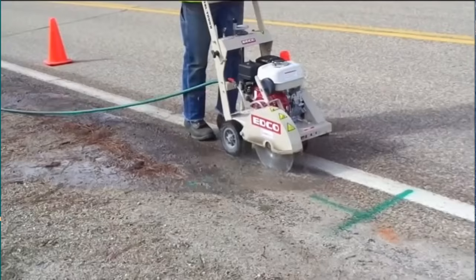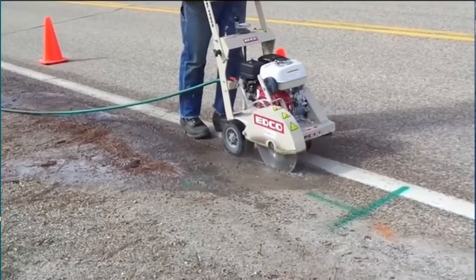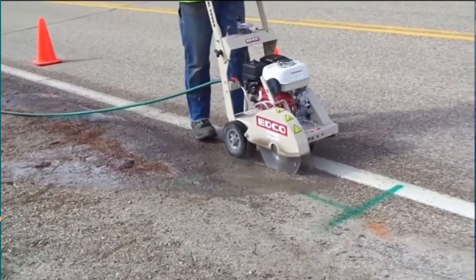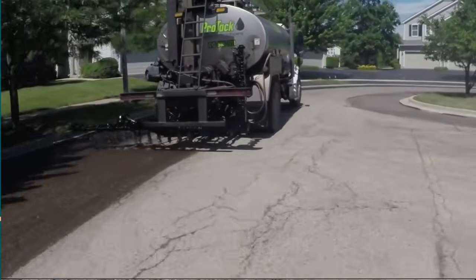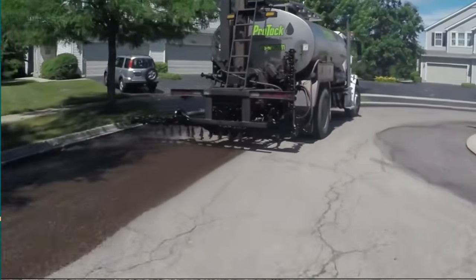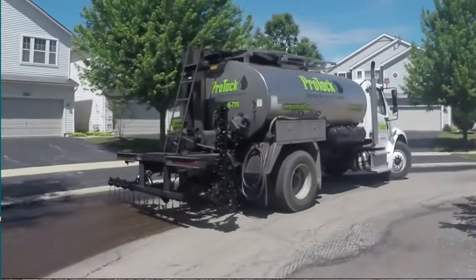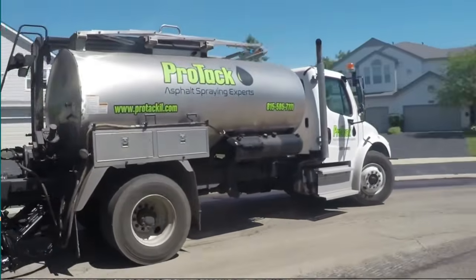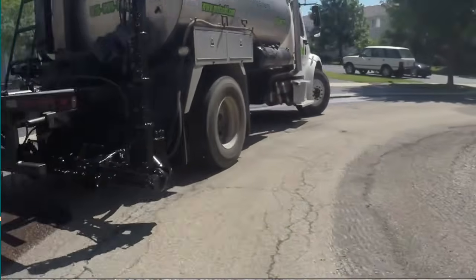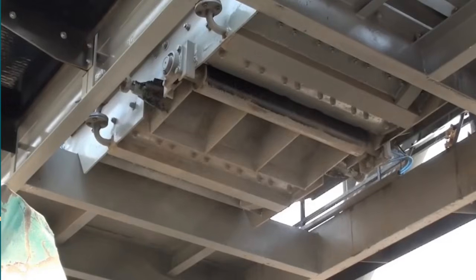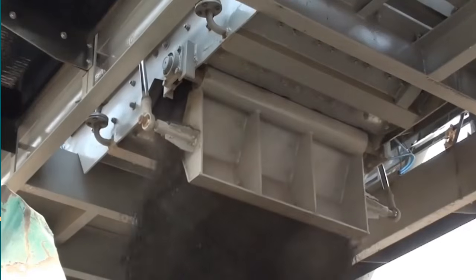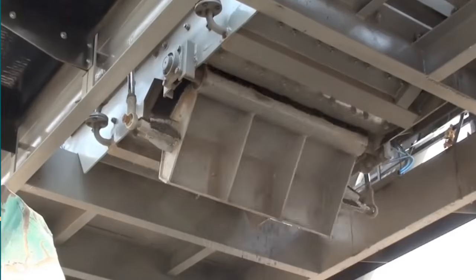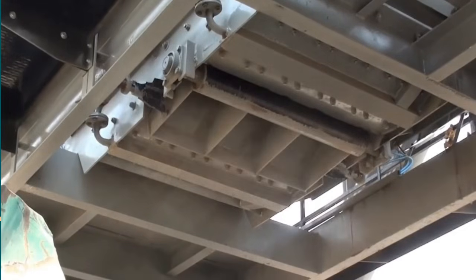The transverse joint shall be cut vertically with an asphalt cutter, and a coat of hot bitumen shall be applied before placing materials. Prime coat or tack coat shall be applied as per the specifications. Preparation of mix. The DBM should be produced on batch basis by weight in a hot mix plant. The mixing shall be done in a twin-shafted pug mill which will produce a homogeneous mix. The mixture shall be transported from the batching plant by tippers.